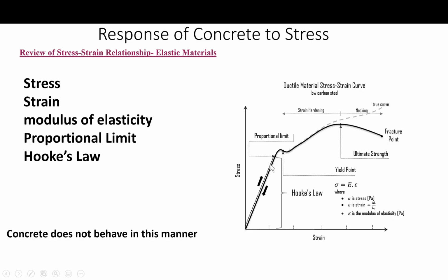area. The elongation follows a straight line up to a certain point. Then we have the yield point after the element has yielded. Then after that we have the strain hardening region, basically the rearrangement of the atoms as well. And we reach the ultimate strength. After that, the material will fail or will fracture rather. Okay, so this is just a general description of the stress strain curve for this element, which is the low carbon steel bar in tension.